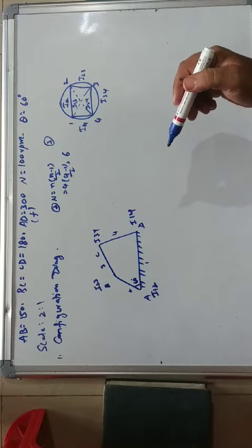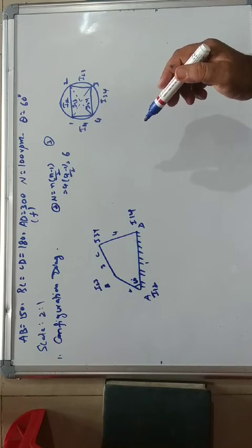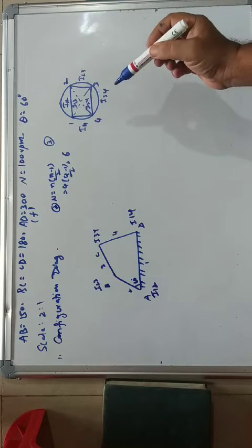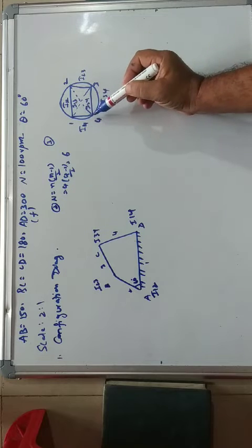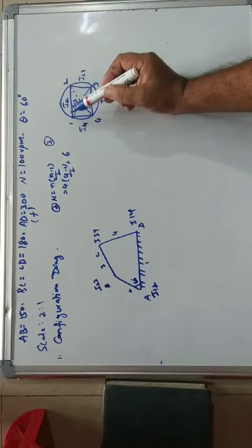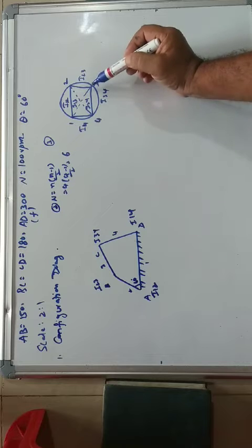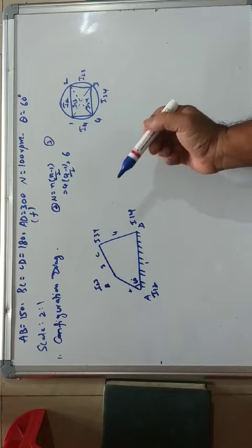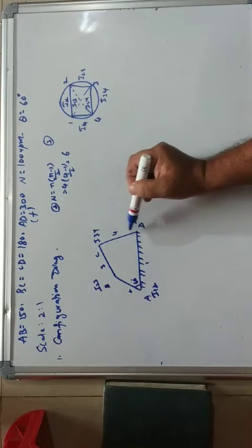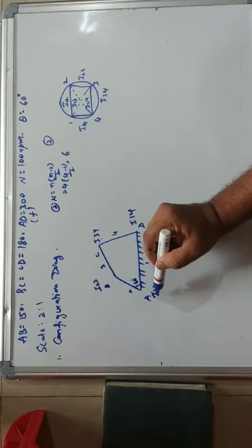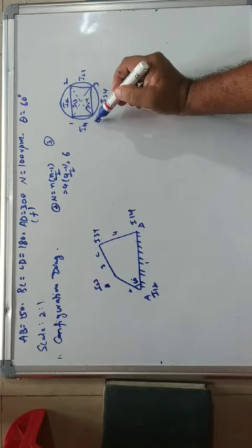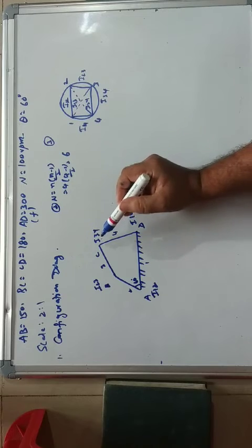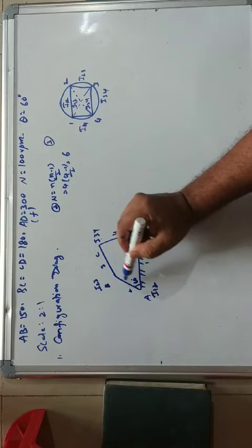After locating these, if I want to locate the remaining 2 instantaneous centers, for example I13: if you see, it is the extension of 14-34 and 12-23.